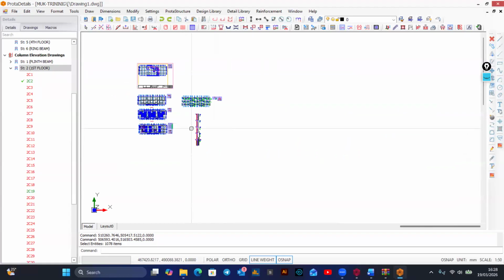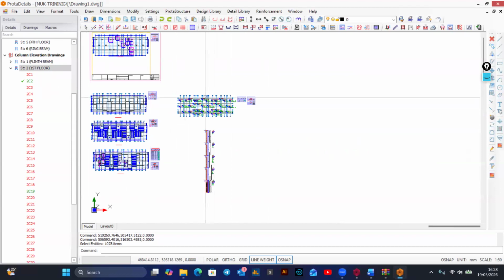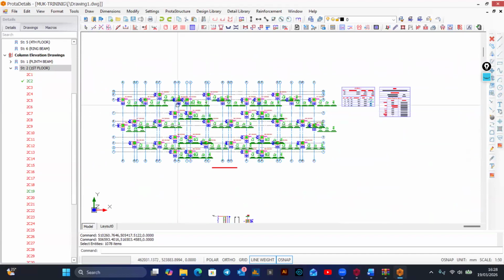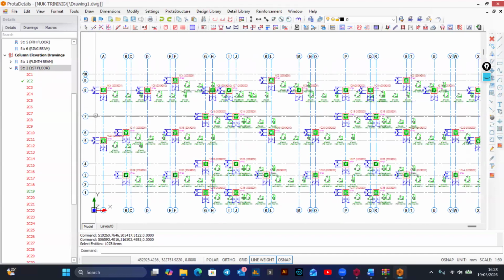But then, how is it supposed to be done? You look at your layout. You are the one who has designed these columns, so there will be those columns that are unique. Look out for unique columns that you have designed and only export those columns to AutoCAD.